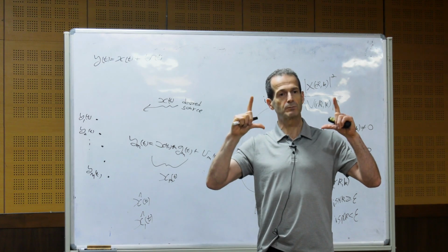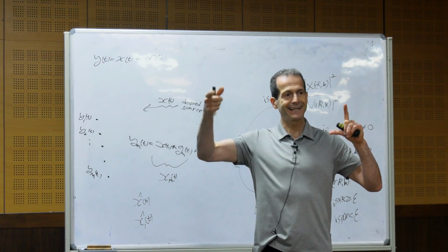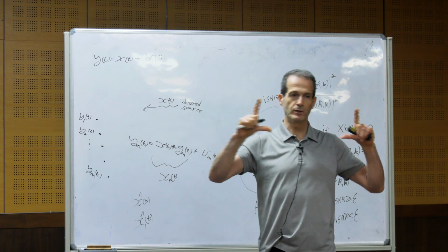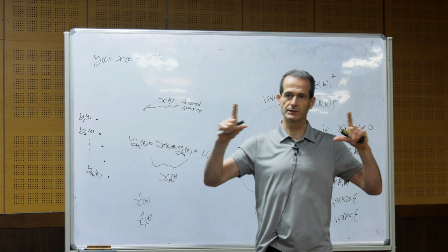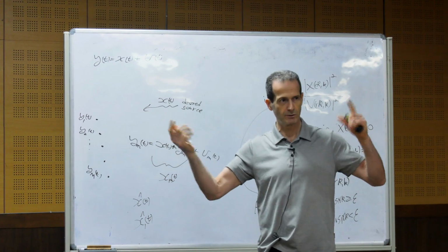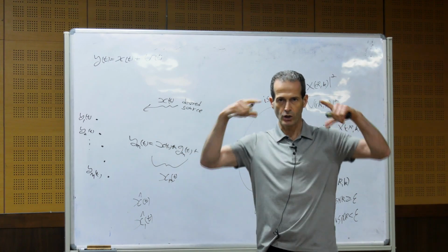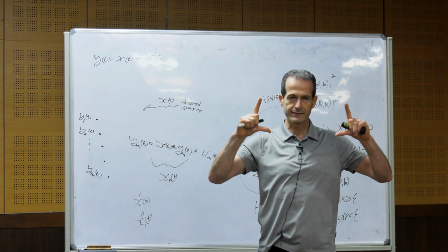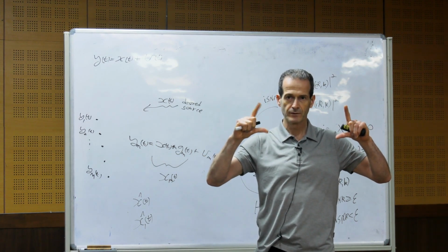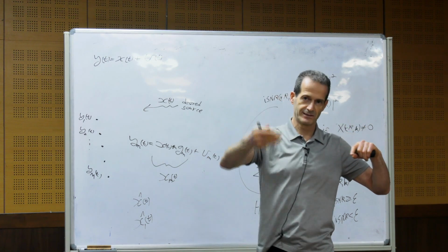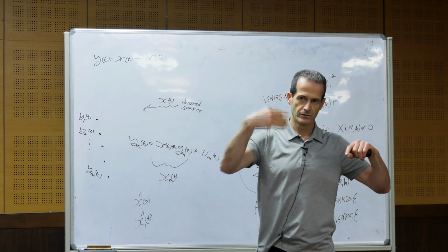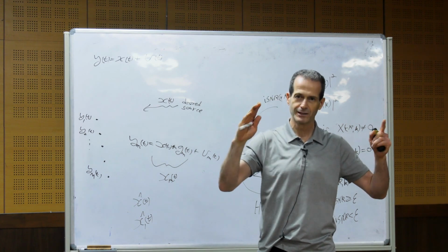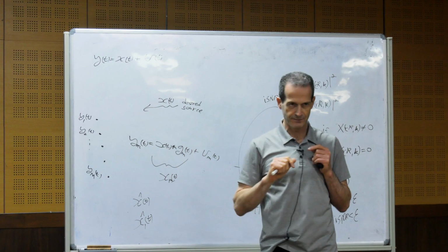So if the image is blurred, and you know the exact impulse response in images, which is the point spread function, so if you know how the object is convolved, and then you get the blurred image, you can take the inverse, okay? So it's called deblurring for images, but it's the same, it's like de-reverberation.